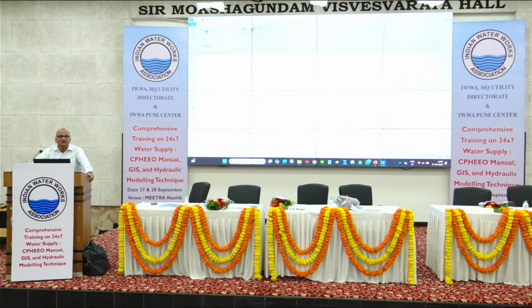Now the next step is, you have to create the model using the model creator. What is the data in your hand? Shapefile of the pipe only at present. And I showed you the shapefile, how you are going to create it for Nagpur, which I already demonstrated in the morning session. So I will create the model right from your shapefile. For that purpose, let me first check my shapefile of the pipe.